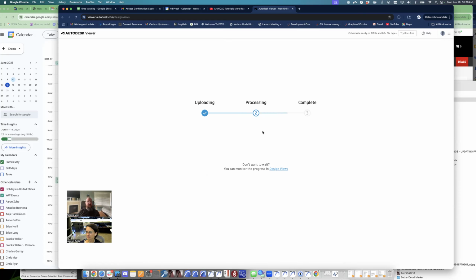They say drawing ID, layout ID. If you give them the PDF, then they know that's supposed to be referencing this section. That makes sense. So I would say do a tip: full PDF set, plan sections, whatever the documents that you have laid out on layouts. Get them PDFs of all of that, and then save out as much as you can in DWG.